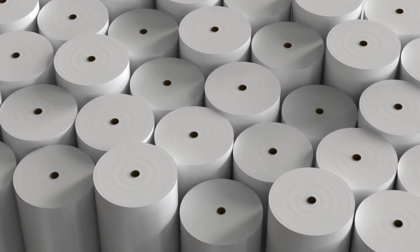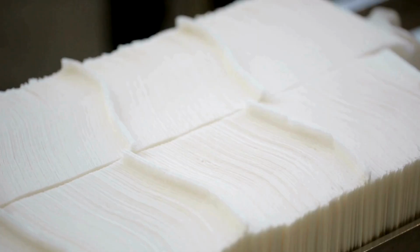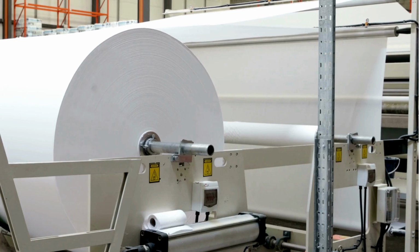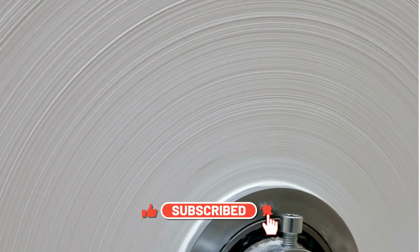The next step is calendering, when the paper is pressed between smooth rollers, calendar rolls, to achieve the desired thickness, smoothness, and finish. The finished paper is wound onto large rolls for industrial use or cut into sheets of standard sizes, such as A4 or letter size, for the rolling or cutting step.